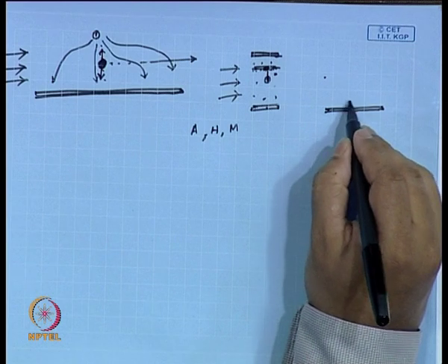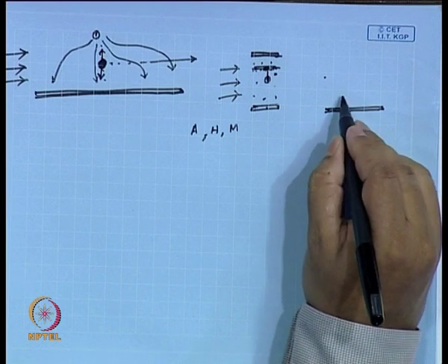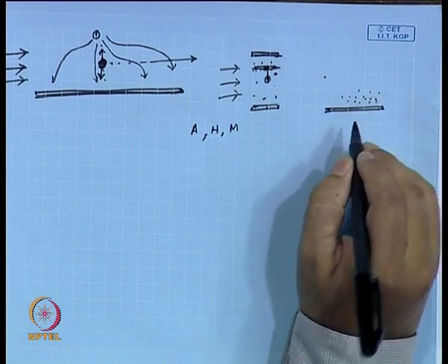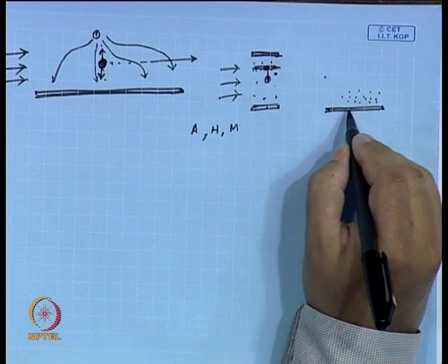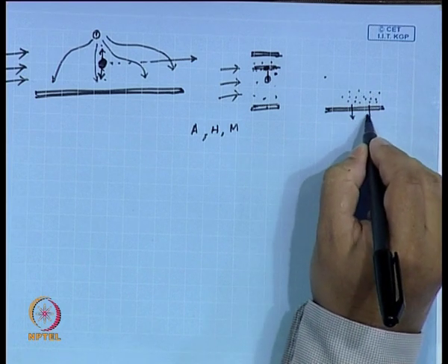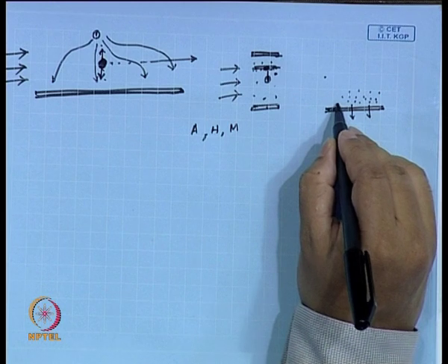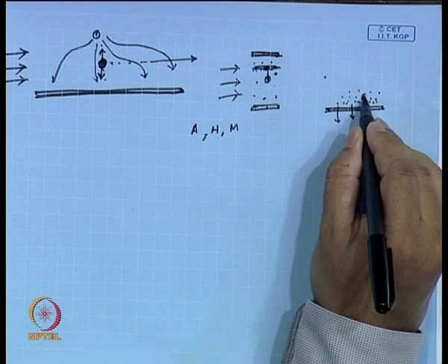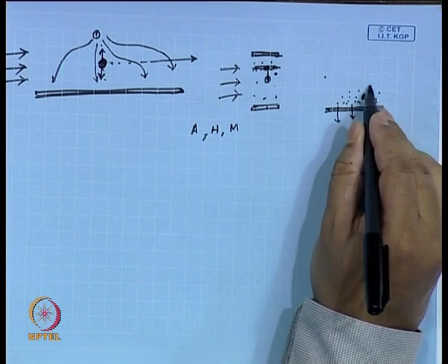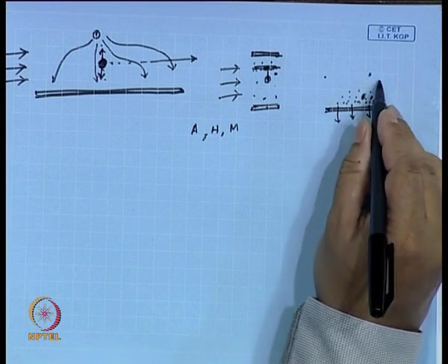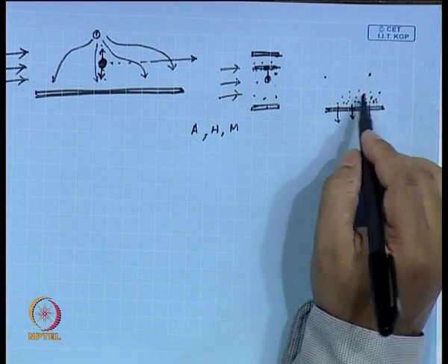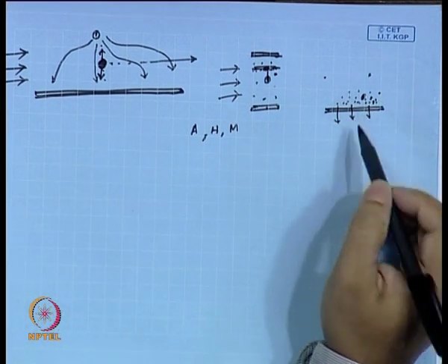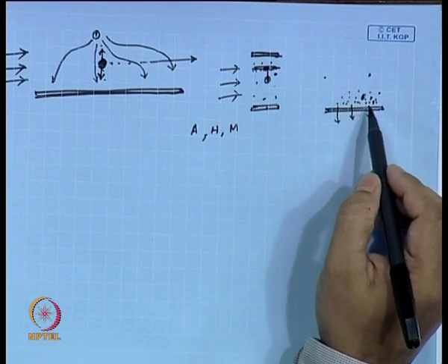So, in that case you have particles plus some liquid, say water, with some other particles in water. Water would be flowing through the membrane and the particles will be held next to the membrane. Now, it would be difficult for the bigger particles to diffuse back to the bulk, whereas for smaller particles it is easier to go back to the bulk. So, there is something called polarization happening, and the particles will be forming bands depending on their size.